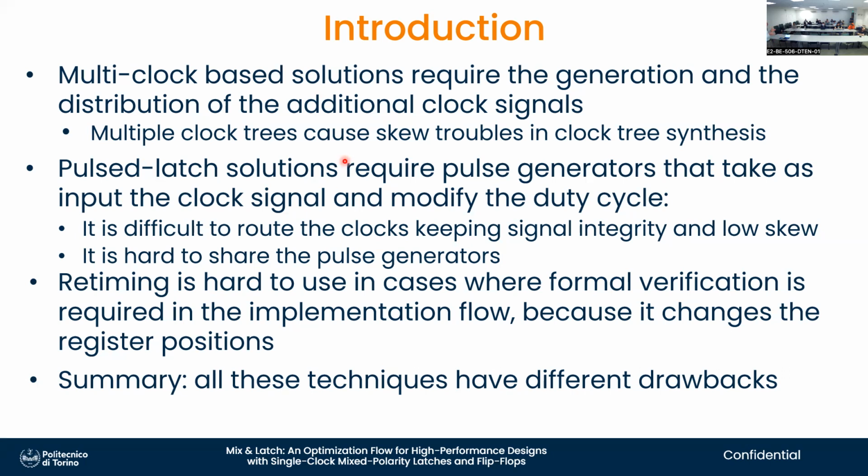In practice, we can solve combinational equivalence checking. So if we keep the flip-flops in the same locations, we can check that the original RTL logic is equivalent to the logic extracted from the layout. If you start moving registers around, you need to do sequential equivalence checking, which is much, much harder. So all the techniques that I described to improve performance beyond what is allowed by keeping the flip-flops in the original positions have significant drawbacks.